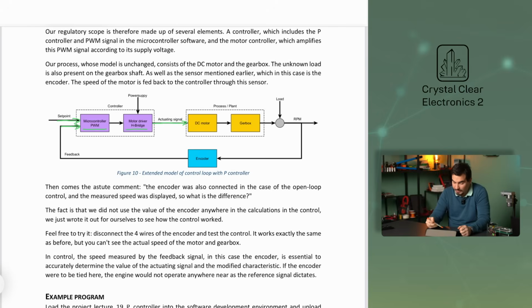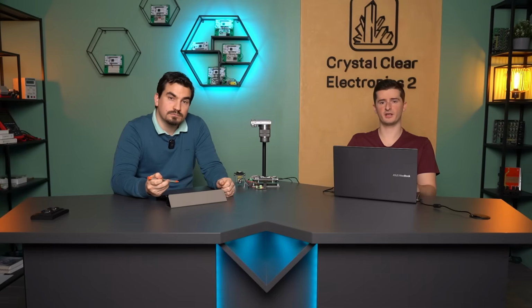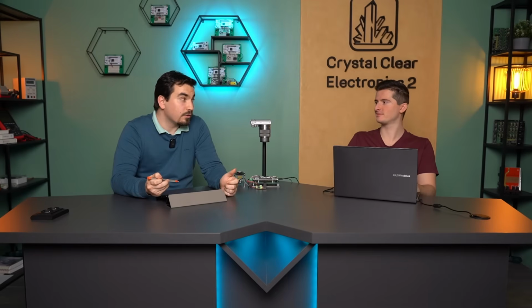Our process, whose model is unchanged, consists of the DC motor and the gearbox. The unknown load is also present on the gearbox shaft, as well as the sensor mentioned earlier, which in this case is the encoder. The speed of the motor is fed back to the controller through this sensor. One might reasonably ask if the encoder was also connected in the case of the open loop control, and the measured speed was also displayed, so what is the difference? The difference is that we did not use the value of the encoder anywhere in the calculations of the control. We just wrote it out for ourselves to see how the control worked.